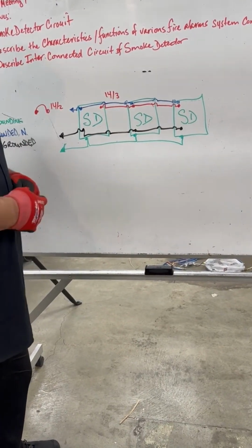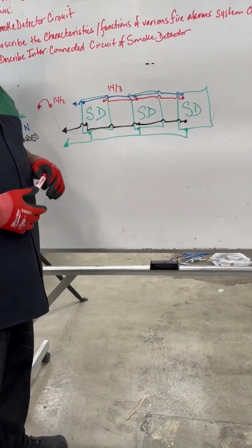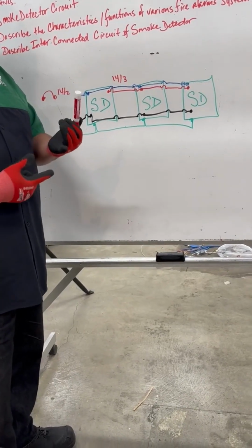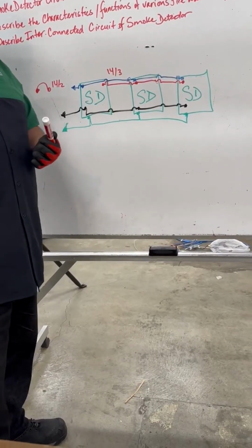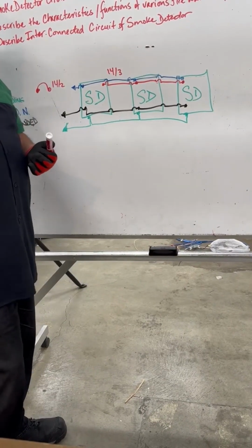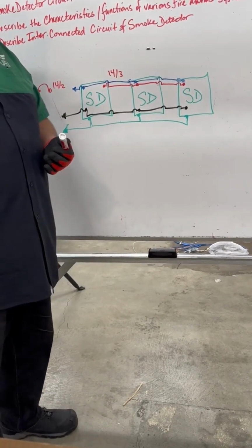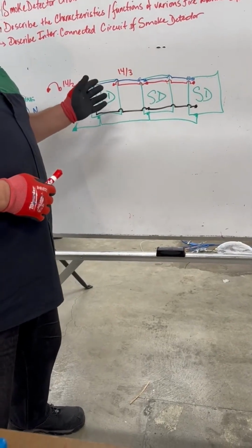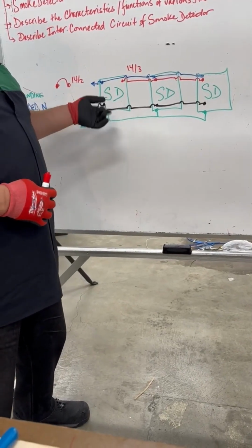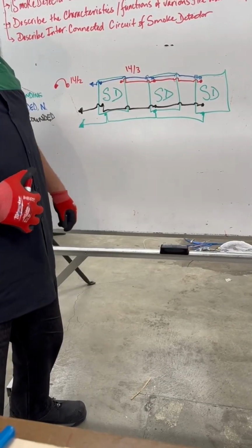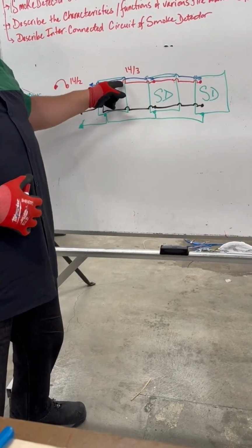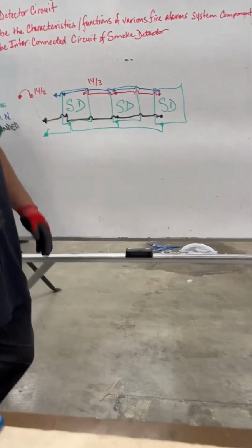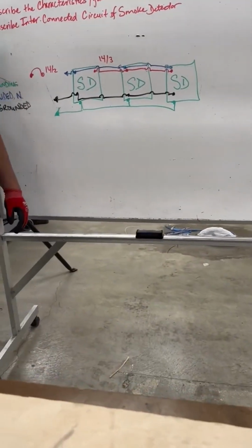It's an easy wire management project for students, but I think we should take it more in depth, taking it back to the NEC, back to the manufacturer's spec sheet, and all the background information they give you on top of that. So it's just like a 1, 2, 3 combination as far as our typical wiring of conductors. The only thing new is providing that interconnected circuit between all the smoke detectors and explaining that concept.